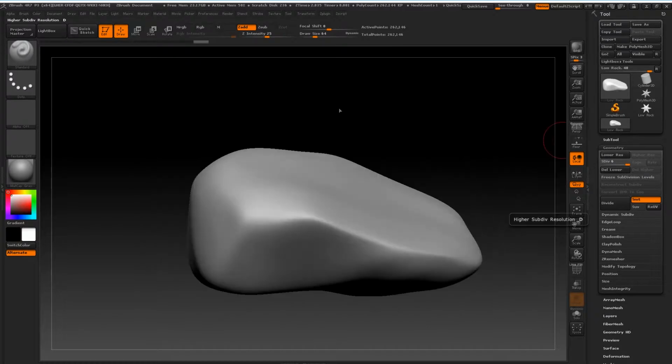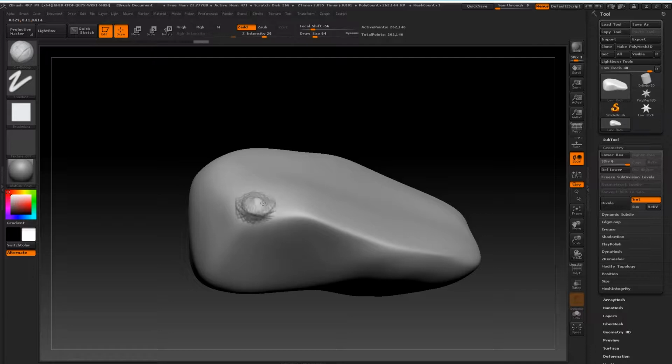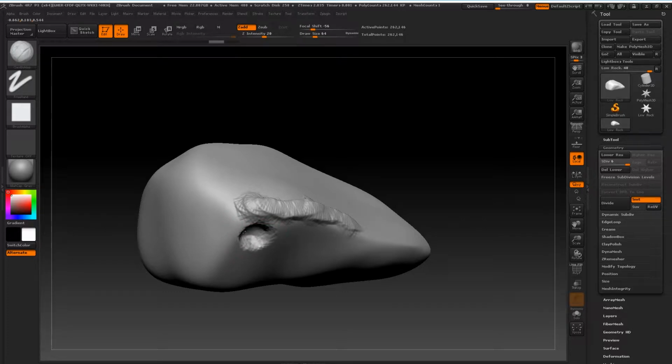To begin sculpting, we selected the clay buildup brush, shortcut BCB, brush clay buildup, and we began to use circular patterns to click and sculpt onto our mesh. We held down Alt to sculpt into the model, and we held down Shift to smooth out sections of the model. We shouldn't smooth too many sections out of our rock.